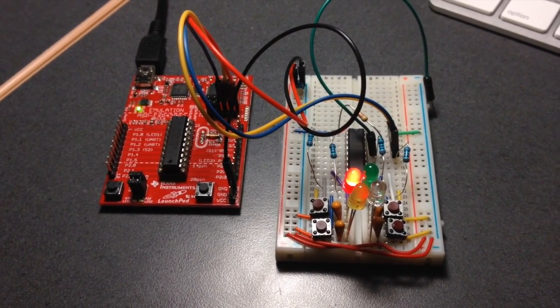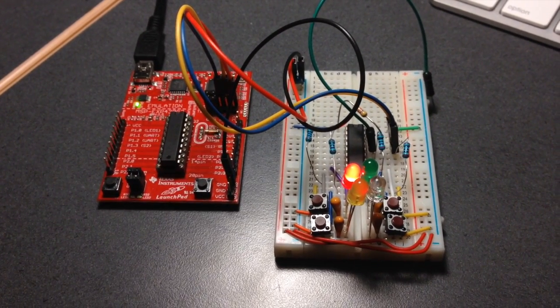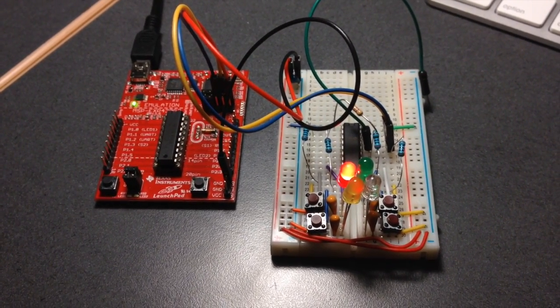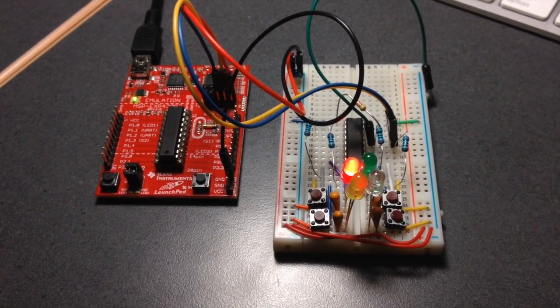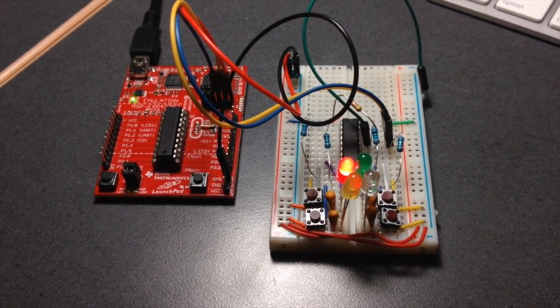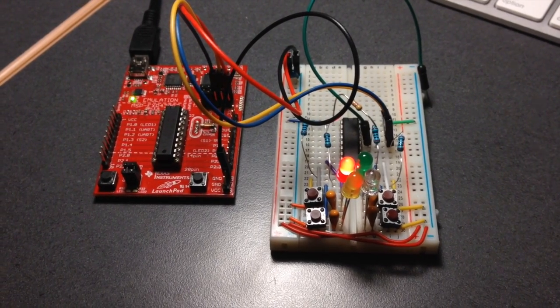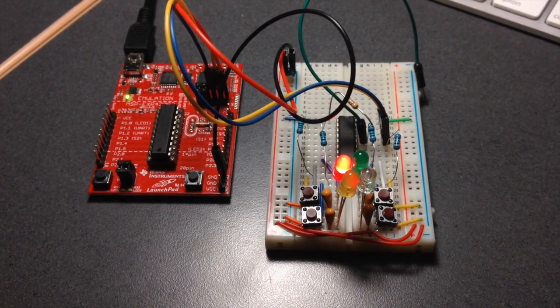The pseudo-random number generator, which uses a bit shifting mechanism, currently uses the exact same seed in this first iteration. In future iterations, it will be done off of some sort of ADC sampling or off the internal oscillator. But for now, it's going to give the same sequences every time, since the seed is always going to be the same.